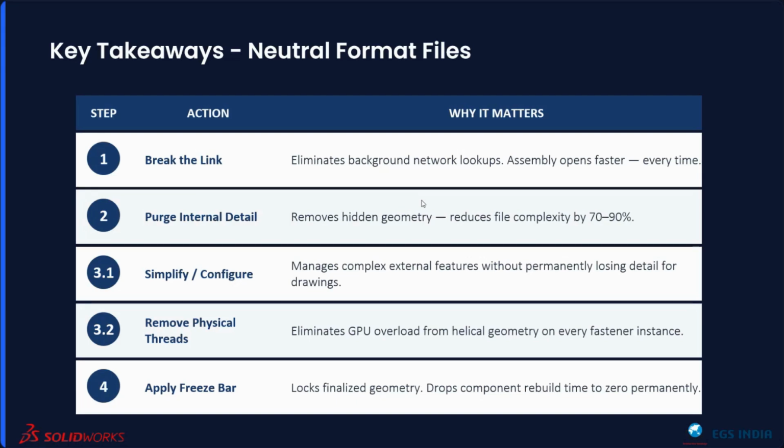By doing this, it reduces the file complexity, it reduces the graphic triangles coming into the top level assembly, it reduces the opening time, etc. For the external features, which might be required in specific situations, we're going to configure them in such a way that we have a simplified configuration for most of our work. And when it comes to the specific purpose, we can switch it to the default configuration.